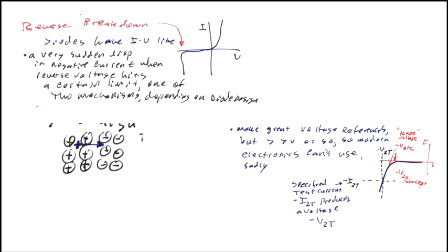So you can imagine if you've broken a covalent bond and made an electron-hole pair and accelerate them, it's very possible that those electrons and holes are going to bump into some silicon atoms and knock off some more carriers. So there's usually a mix of those, and you can actually kind of figure out what that mix is, but we're not too worried about that, or I'm not going to worry about it.